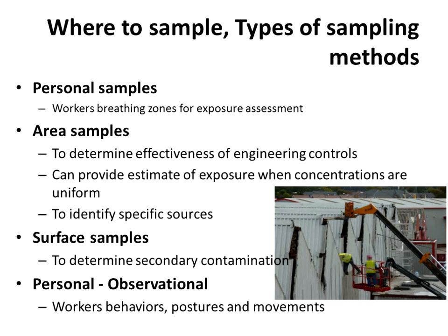Area sampling is where you draw a volume of air within an area such as a room. I guess it's not a good interpretation, but instead of being right next to the worker's jaw, you're trying to draw a volume of air into usually a bigger container like a bag or a cylinder, and to characterize what's going on in the entire room. It'll also evaluate the overall effectiveness of engineering controls such as fans and ventilation that are being used.